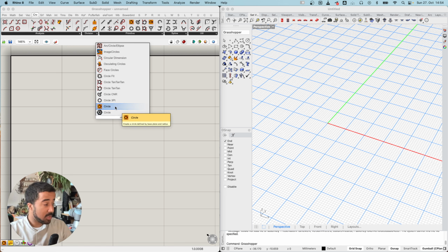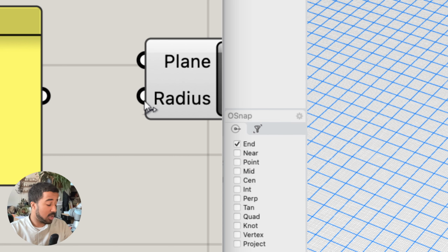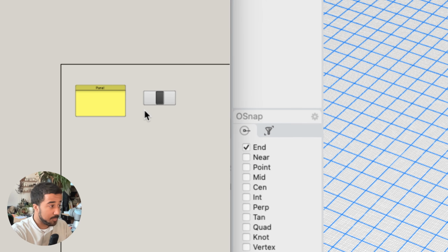If I want to disconnect two components again, I can either right click on an input and select the disconnect option from the menu, and then the components are disconnected. Or when they are connected, I can connect them again but hit Control, or if you're on a Mac, hit Command, and then you will see that the icon next to the cursor changes to a red line and a minus sign up top. And then if you connect something, it will disconnect the two components.